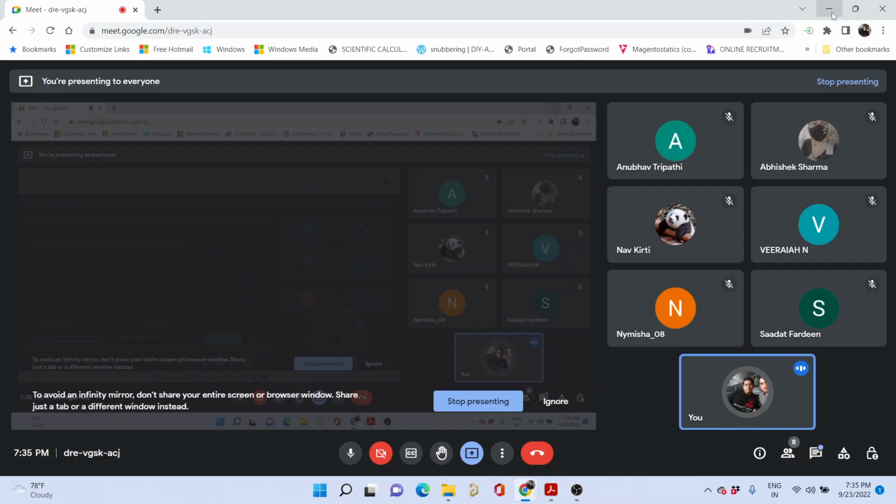Whatever you have learned is the mathematics portion, the mathematical modeling of the system. You replace S with j omega, but whatever you propose mathematically, you also have to prove experimentally. So this is how we actually go for it. That's why we replace S with j omega, because we are concerned with the output to sinusoidal functions of certain frequencies. Okay, so I would go through the solution again because I have done a very similar sum in the previous class.